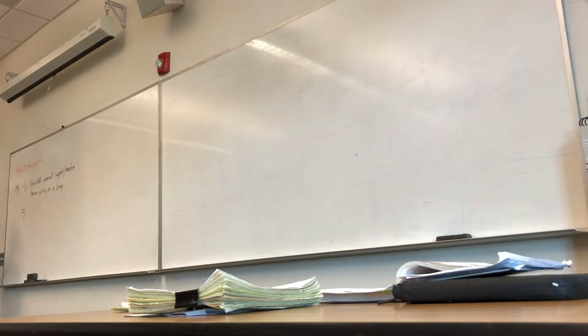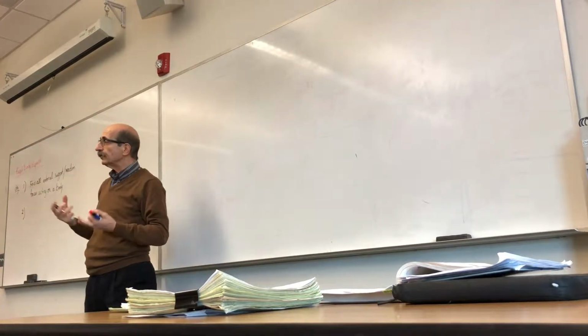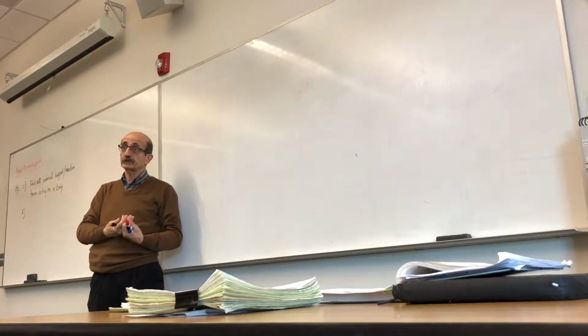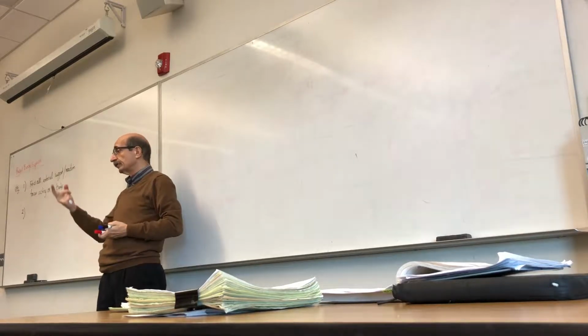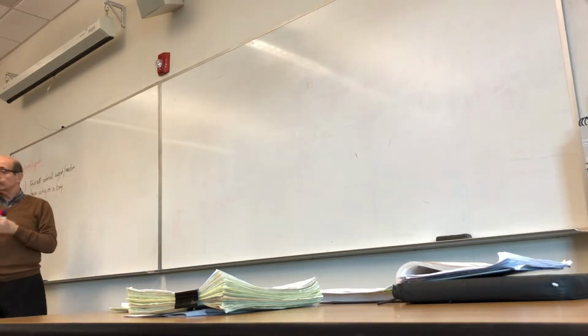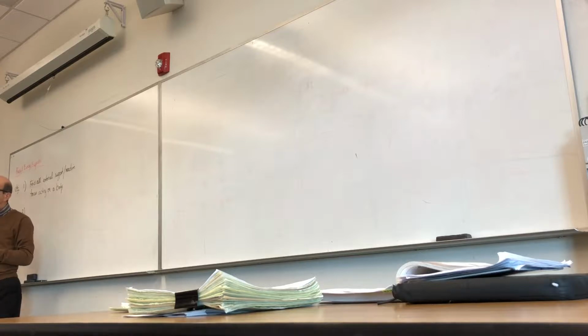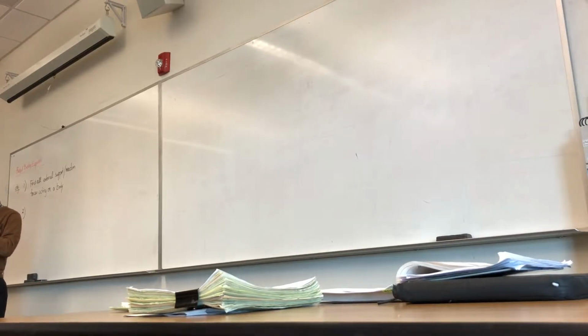Objective number two: any structure, at least those that we are dealing with, is made of components that are connected together. The chair you're sitting on is made of legs, the platform, the seat. These are all pieces that are connected together. So to design this structure, it is important to know how to connect these pieces together, weld them, bolt them, glue them, whatever, right? So you need to know, as you take these pieces apart, what are the forces that are needed to put them back in one piece. The connection forces, the joint forces.